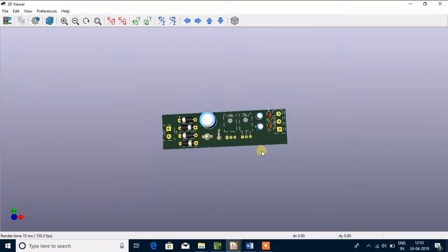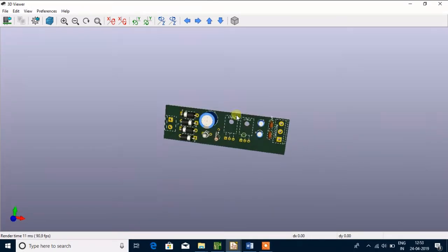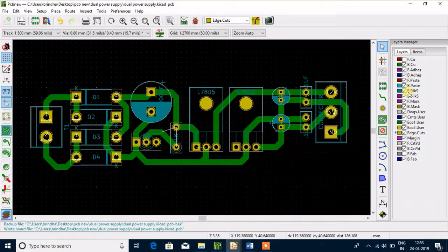You can notice that there are more edges or left out spaces. You can cut all those edges using the edge cut icon. How is that so? Let us see. Now click the edge cuts in the right side icon. After clicking that, click add graphic lines.